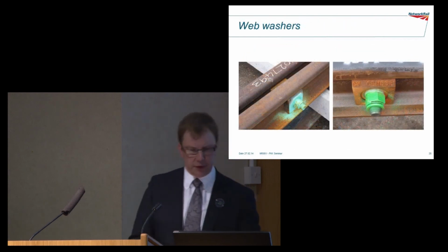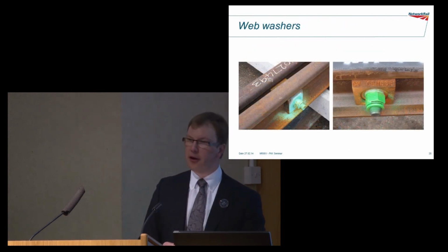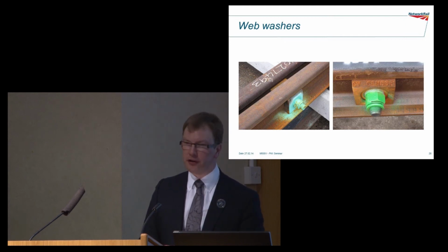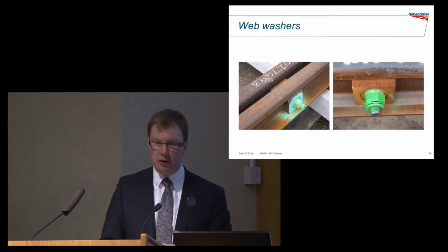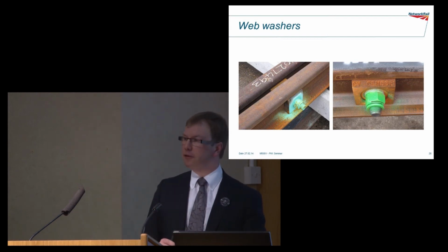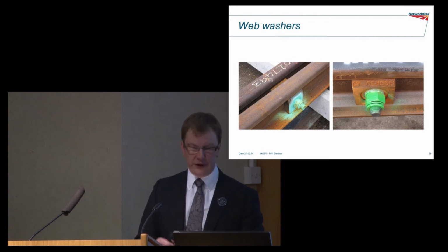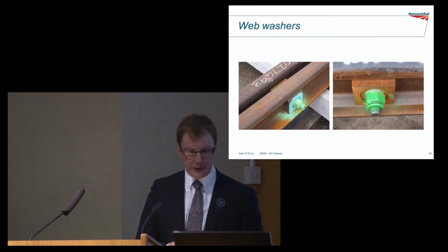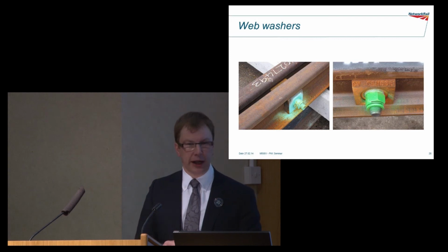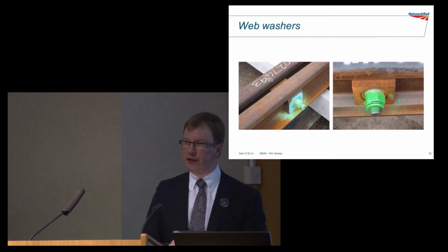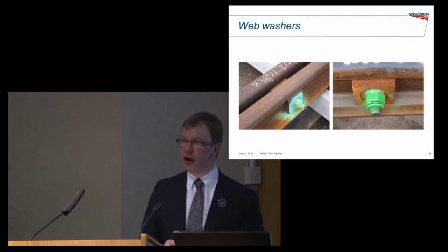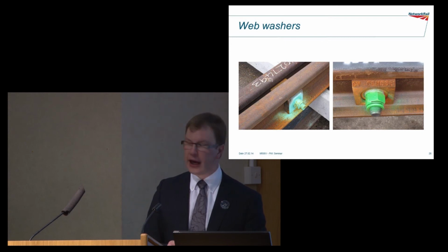Now the web washers, these were the things that caught us out. So this is an arrangement for a distance block. So we fitted these web washers on the outside of the joint for a number of reasons. One, because it helps to spread the load from the bolted joint. Another reason, because it actually gives better access to the nut to enable the joint to be torqued up properly. But what we overlooked when we built the pilots was the fact that you can't fit point heating strips. So we have now got a modified design which has been trialled on some of the original layouts, and that's now being incorporated into the standard drawings.